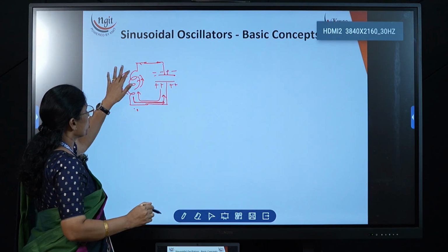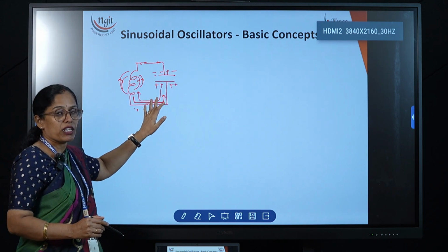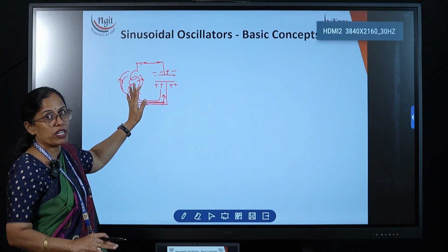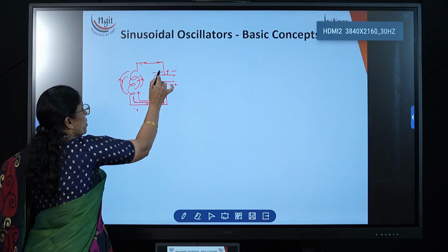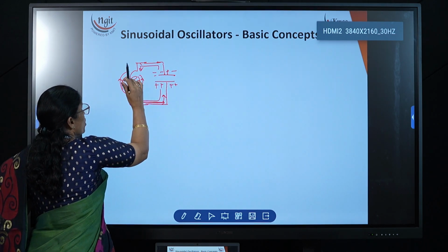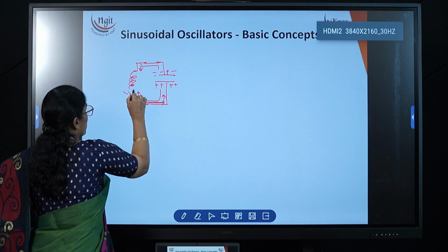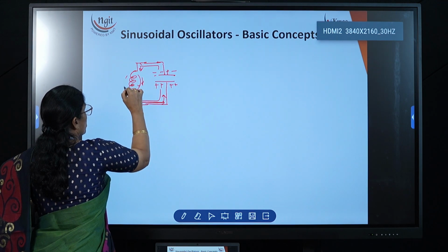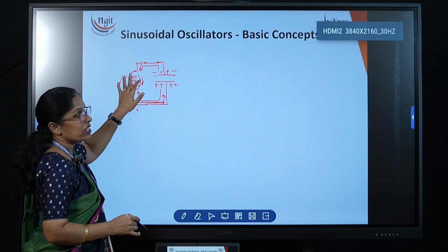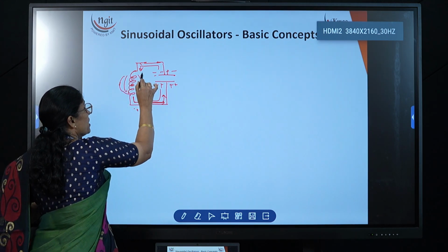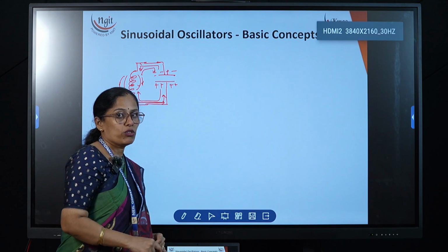It will charge positive over here and negative on the top. So after completely discharging the inductor, the capacitor is again charged. After the inductor has completely discharged, no current is coming from the inductor. At that time the capacitor again tries to discharge. In which direction will it discharge? Now here negative is there, so in this direction it will discharge. Thereby the electric field will be set up across the inductor in the opposite direction. Now after completely discharging the capacitor, again the inductor will try to discharge, in the same direction in which the current flowed through the inductor. This is because of Lenz law.